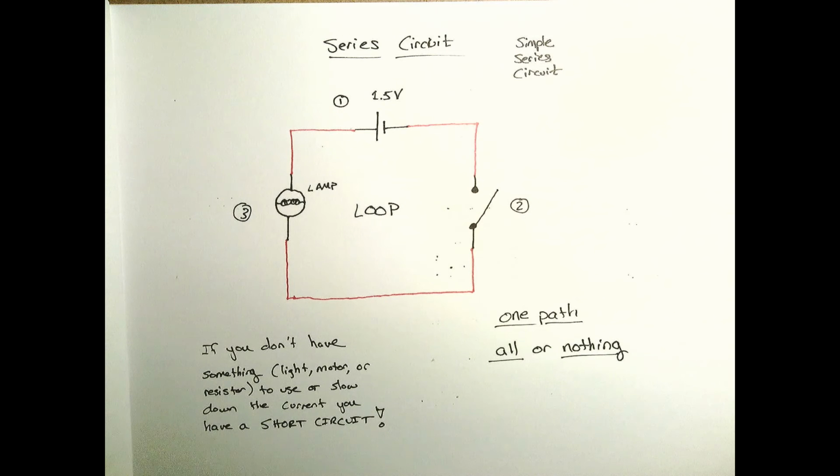Parker: And when you said you have a breaker, can't your breaker go off if you have too many things on one circuit? When you have too many things on one circuit, it's drawing too much current through the wires. And then your breaker goes, that's dangerous, turn it off. And then the breaker goes, whew, job done. Well, you go out there and flip it, and if you didn't make any changes, the breaker flips off again. It keeps clicking off until you adjust how much current you're drawing through that circuit.